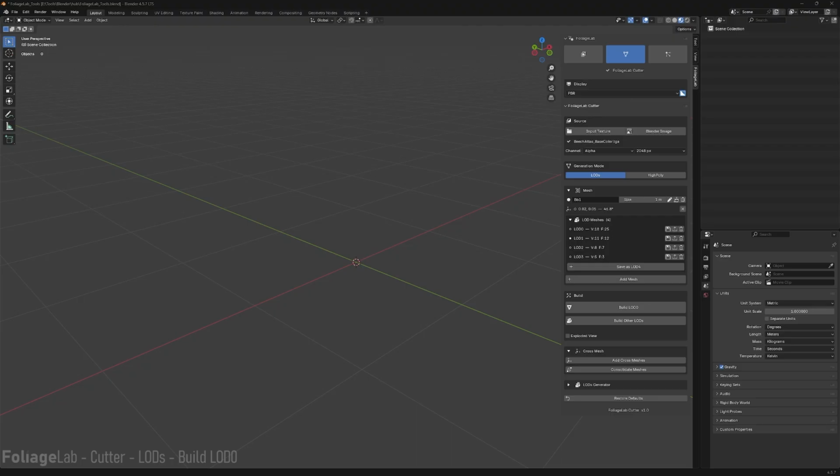Let's go. The generation is split in 2 ways. The first one is to build the LOD 0 first, all the best LODs of each actor you decide to cut. Like that, you will be able to see if each actor looks exactly as you want, if everything is okay, and rework them if you need. And once, and only once, you are sure about your LOD 0, you'll be able to generate the other LODs. The goal of that is just to stay organized a bit, because it can become really, definitely messy.